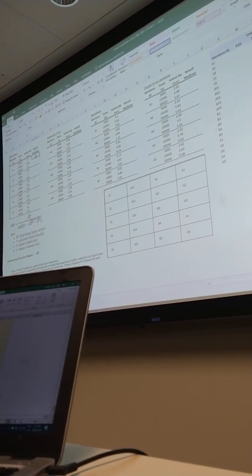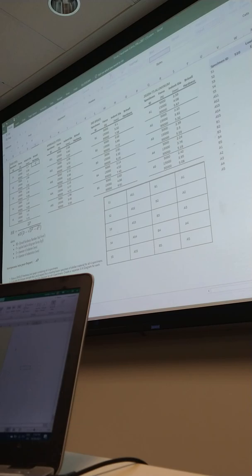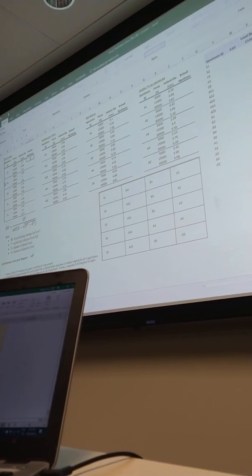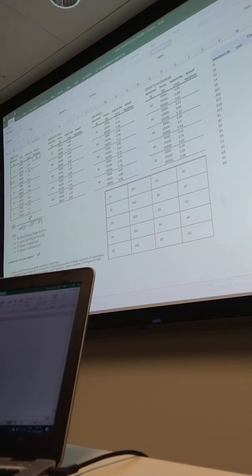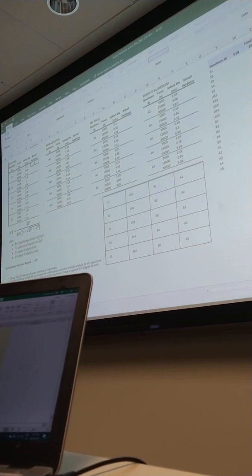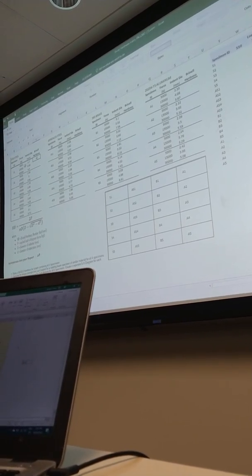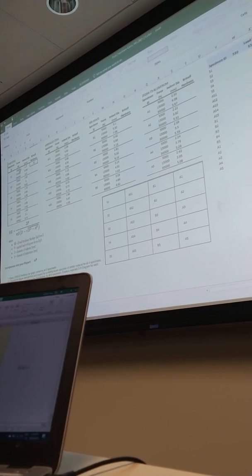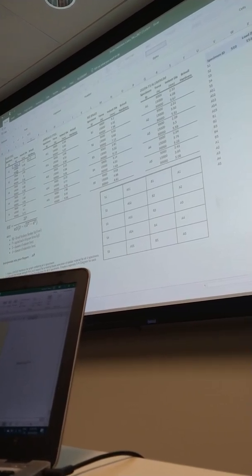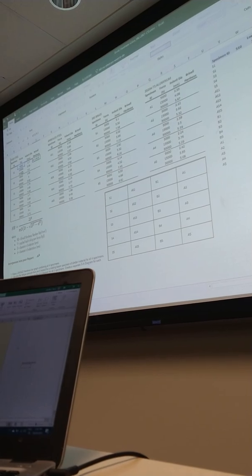So we have, and we're given force, right? This equation only accepts kilogram force, not newtons. We need to change 5,000 newtons to kilogram force. And to do that, you divide by 9.8, gravity.